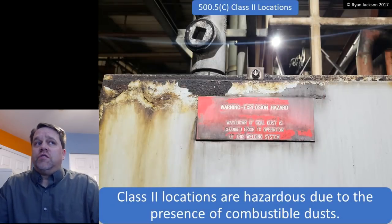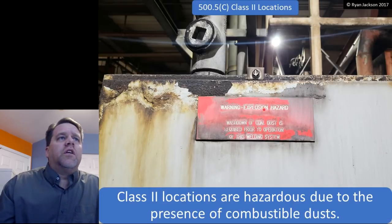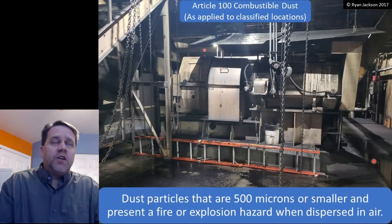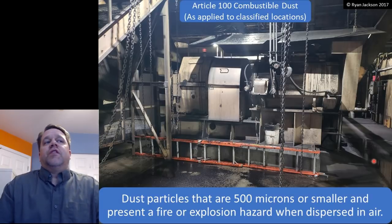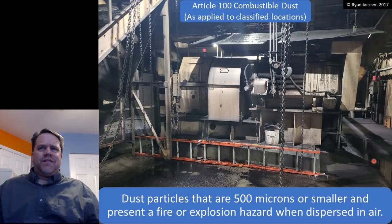We move into Class 2 locations. Class 2 locations are hazardous due to the presence of combustible dust. All right, so what's a combustible dust? And you can see here, warning, explosion hazard, washdown of coal dust is required prior to operating the equipment. Yeah, coal dust is a combustible dust. Combustible dust is defined in Article 100. It's dust particles that are 500 microns or smaller that present a fire or explosion hazard when dispersed in the air. 500 microns. What does that mean?